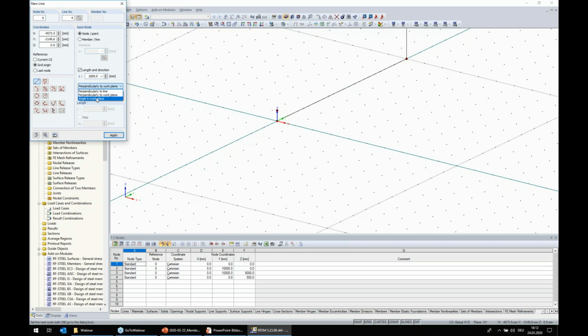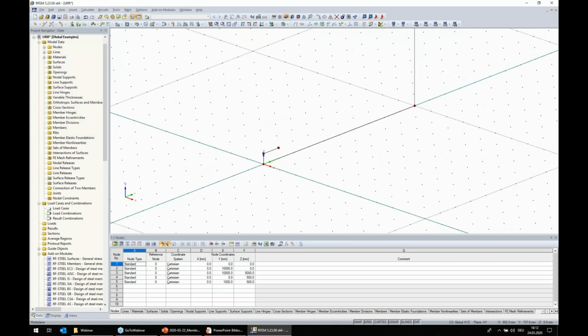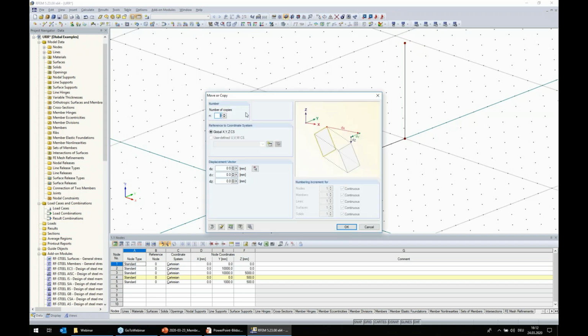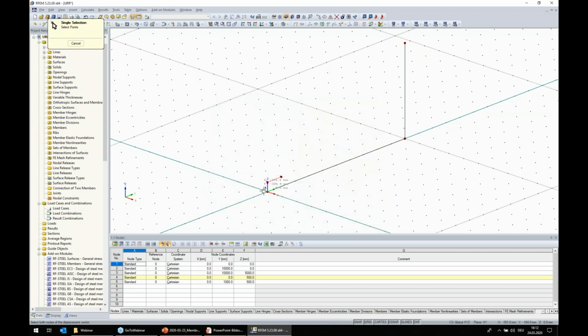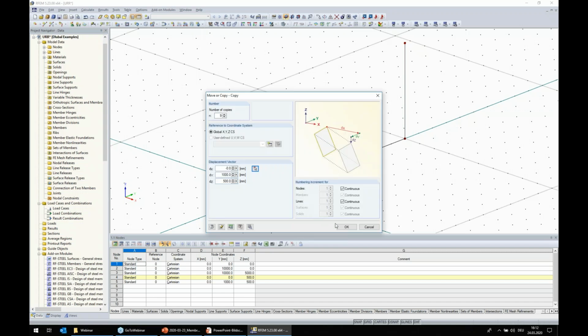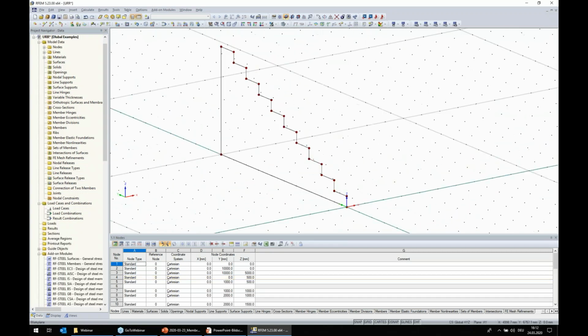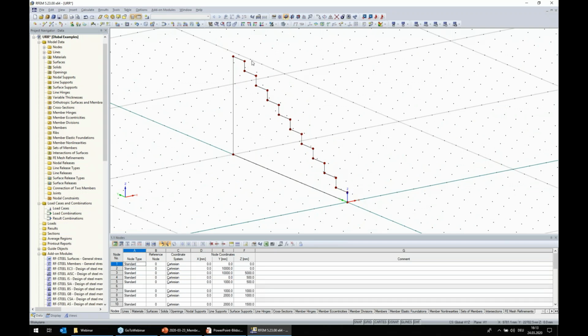1 meter in plane. This type of step we have multiple times; globally we have 10, so we copy it 9 times upwards with the copying vector from here to here. And this is now the cross section of this construction where the people can sit.